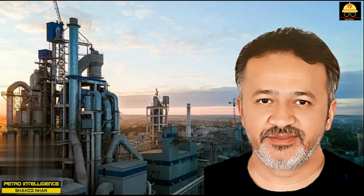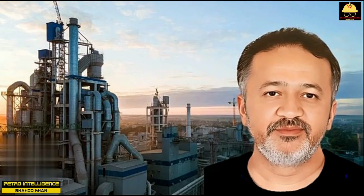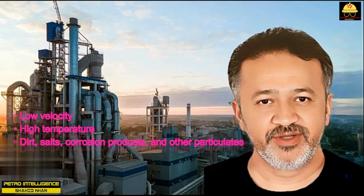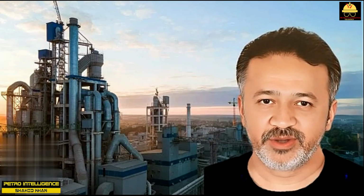Let me explain. Let's assume we have a new heat exchanger. The fluid on the tube side is crude oil. Crude oil, like many processed fluids, will eventually foul and plug heat exchanger tubes. The tendency to lay down fouling deposits is accelerated by low velocity, high temperature, dirt, salts, corrosion products, and other particulates. The crude oil is being heated by a hot oil stream circulating through the exchanger's shell.